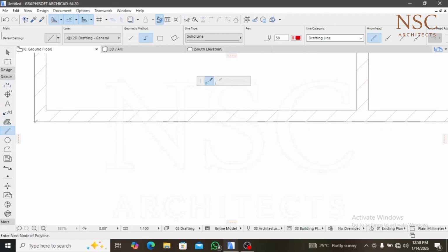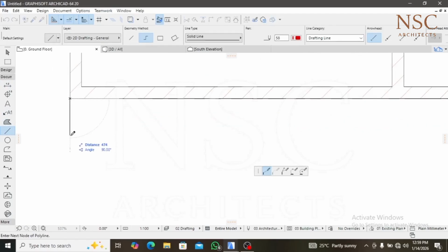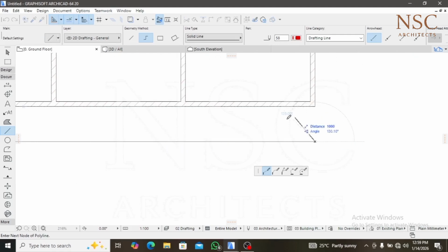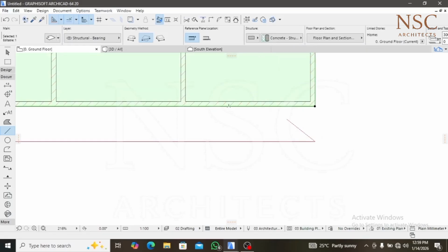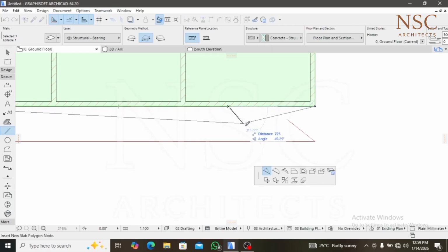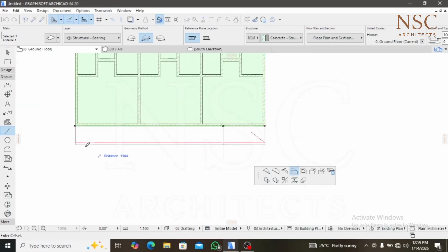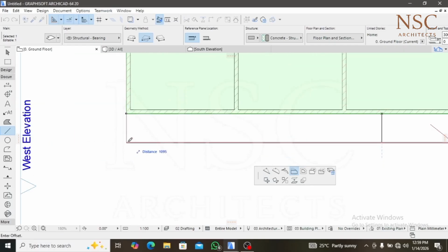You hold your Shift. So to extend your slab, click on your slab, drag it, then look around here, we have commands here. So you come to Offset Edge. You click on Offset Edge, you see. Drop it at the core. So I've dropped it. Then let's delete the line. You click Backspace, delete this off.